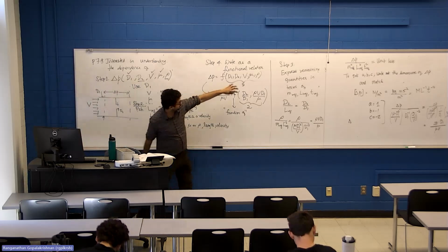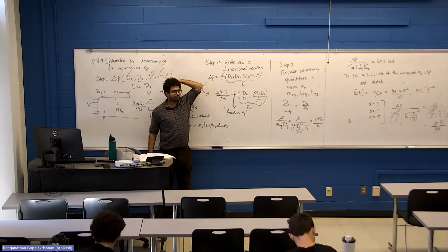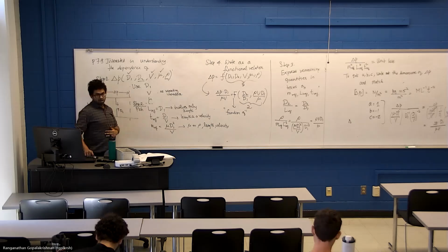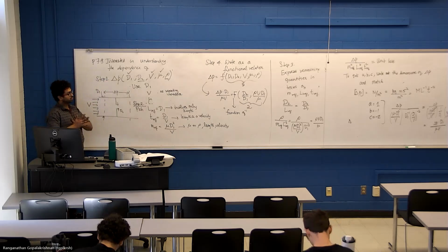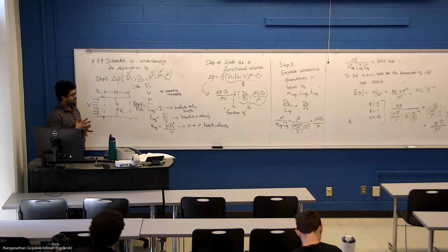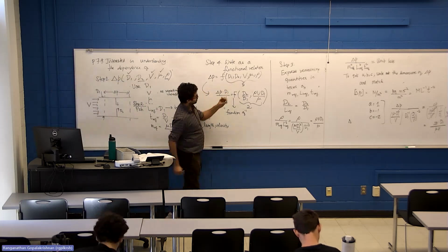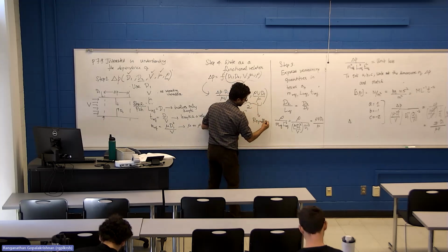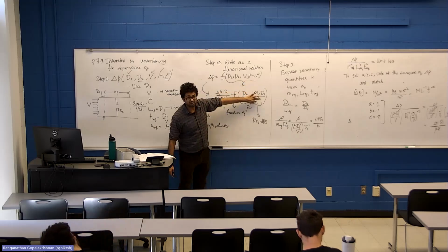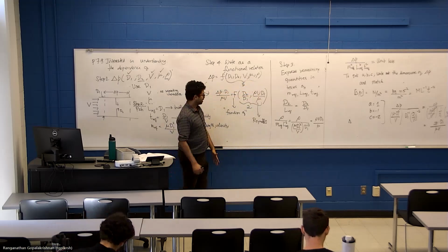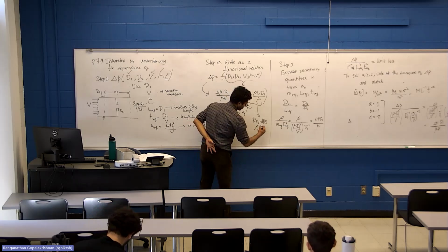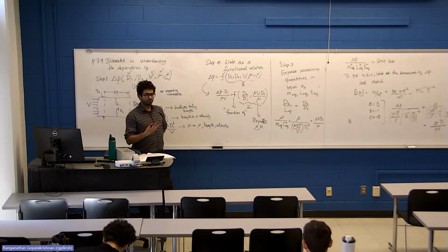Do you look at this ratio rho V D over mu and recognize it from somewhere? We'll continue this next lecture. This rho V D over mu is the famous Reynolds number. For any fluid flow problem that involves density and viscosity, Reynolds number will show up. It will always show up if the fluid has a density, which it will, and if the flow is viscous, in most cases.